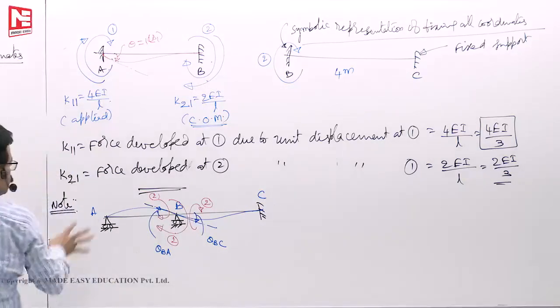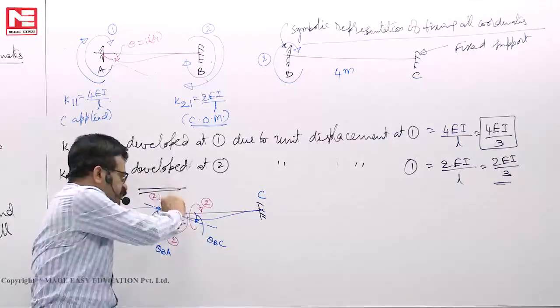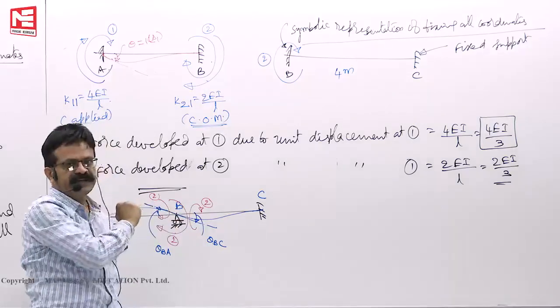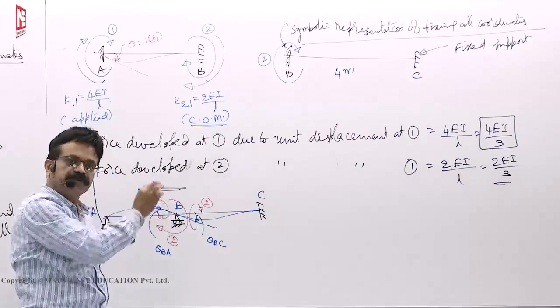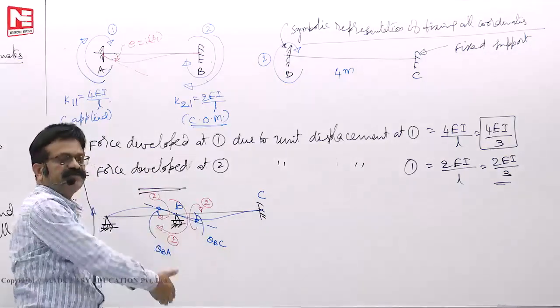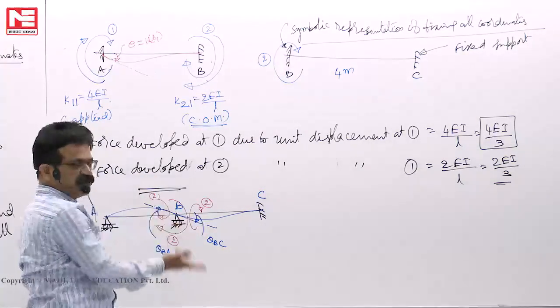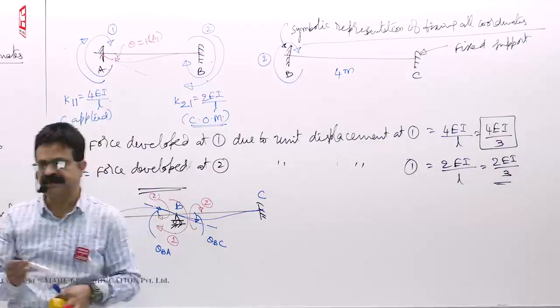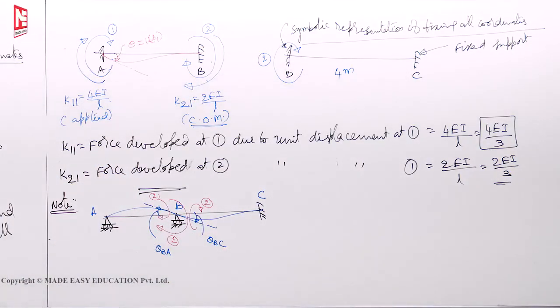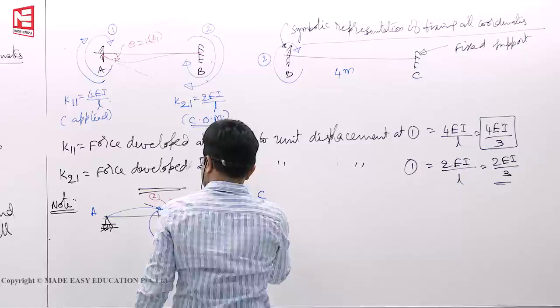Okay. Now we are developing a stiffness matrix by fixing all the coordinates, all the displacements, and finding the force required to produce unit displacement. Then for the actual theta displacement, how much is the force? Linear interpolation we will do and find in 2 minutes time. See here, this is the conclusion.